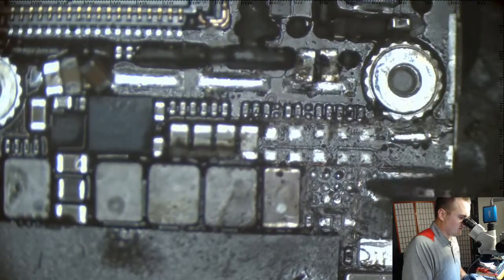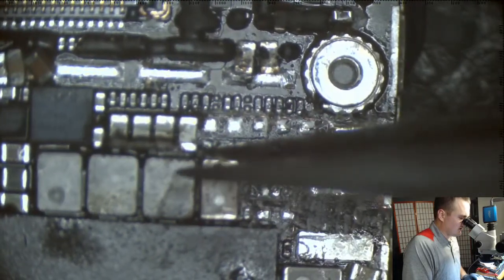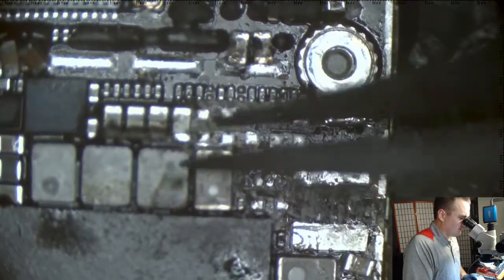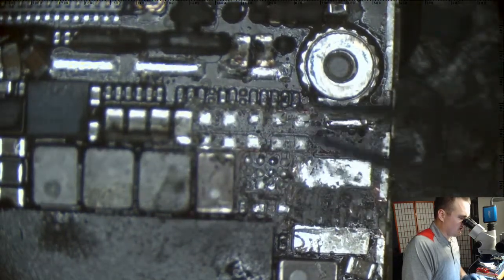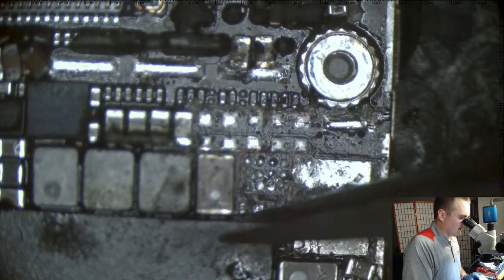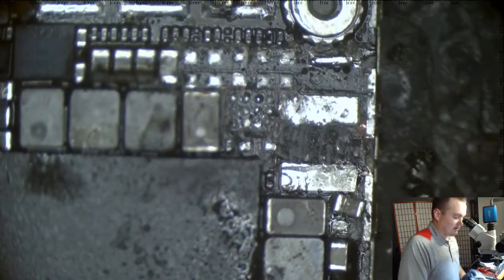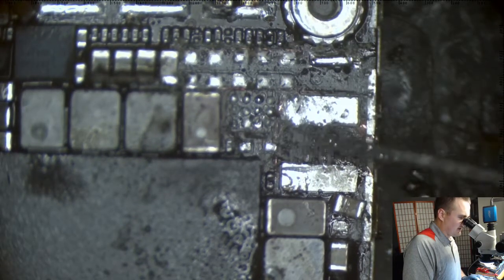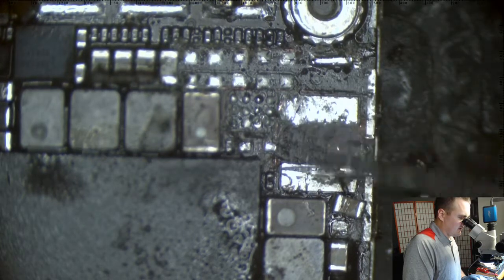What I've been doing for those touch ICs is just reballing the touch IC with a considerably lower melt paste. So the most heat that it undergoes is during removal. And if you're precise about when you remove the chip at the exact moment, it's going to come up without melting all this other stuff. You got to get it as soon as it's sufficiently melted. You go before, you're going to pull pads. You wait too long after, then you're transferring heat.